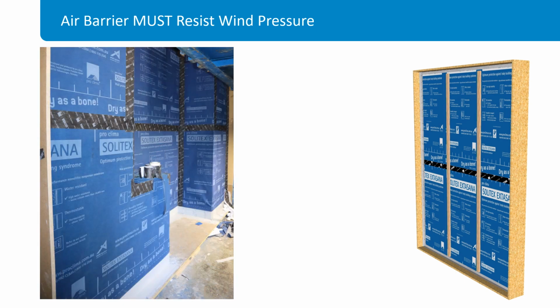The weather-resistive barrier generally sits behind the cladding system, and it manages that wind pressure behind the cladding. So the cladding systems in a well-designed system aren't airtight, and they're not 100% watertight. They've actually got gaps and cracks in them, which means that the weather-resistive barrier behind that cladding is actually the air barrier and the water barrier that sits behind that cladding system, and makes the whole system function properly as a weatherproof system.